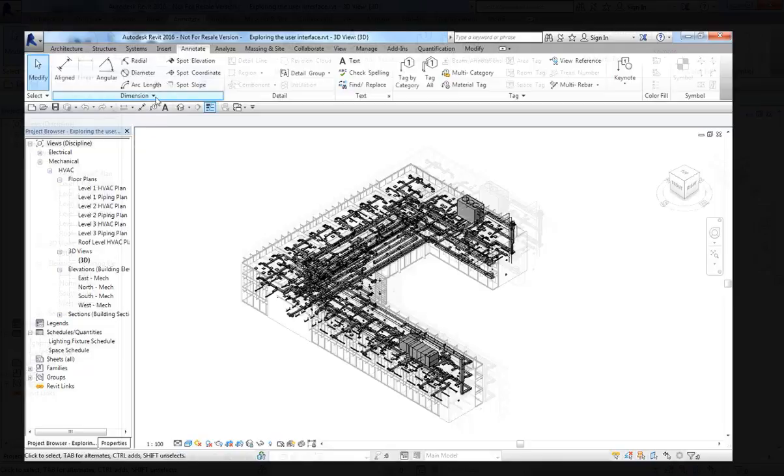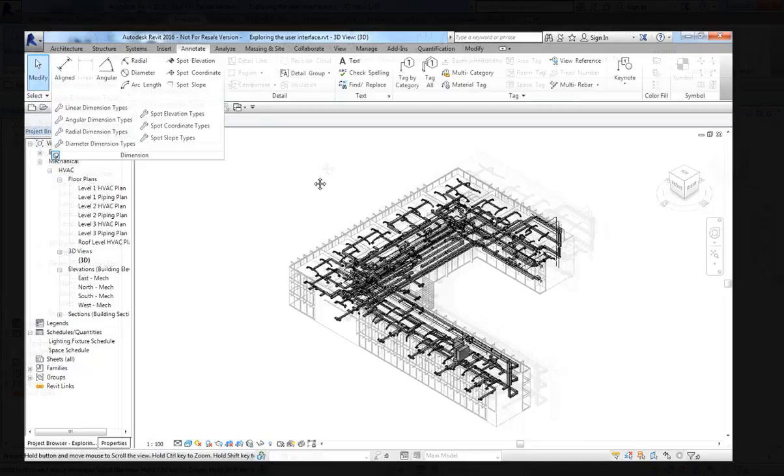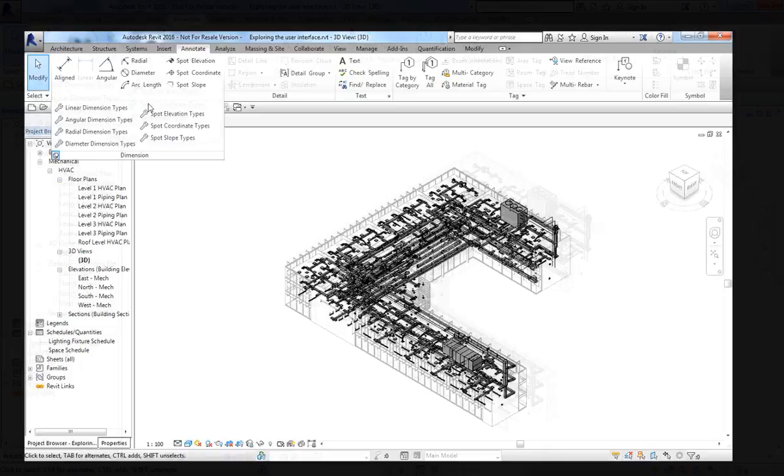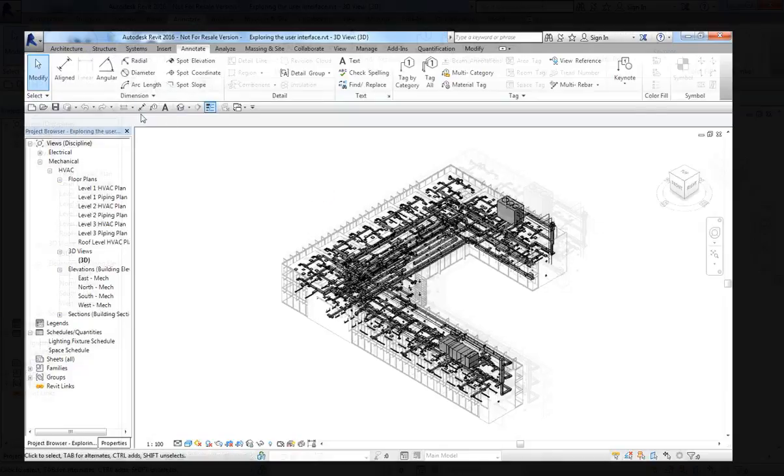So you can temporarily pin an open expanded panel. If I click this, you see there's a pin here. If I put my pointer back to the drawing area, you will notice it will not disappear. It will not be hidden. Why? Because it's pinned. You can pin that, and also you can unpin it. Just click again, put your pointer back here, and it will be hidden now. So that is what you call an expanded panel.